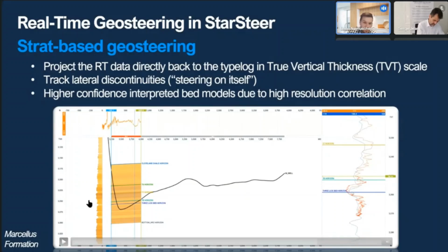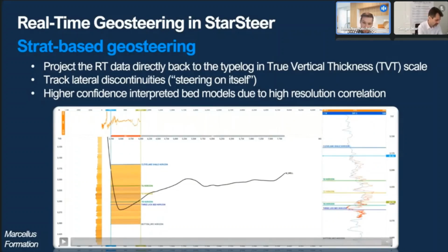And when we start drilling, we reach the deepest point of our trajectory. We've got this data, and when we drill back up to the same formation, we started to receive the same logs. We were crossing the same formation, and we can correlate this log on itself. And here, when we reach this point, you can see these small layers.